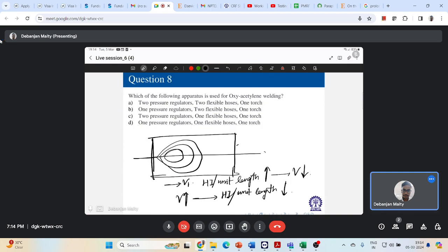Now, one more thing I want to mention over here. Let's say you are keeping all the variables constant, right? And you are changing your welding speed. So with all variables held constant, your weld penetration depth will attain some maximum at an intermediate speed. And if your welding speed is excessively low, the arc strikes a large molten pool, and your penetrating force gets cushioned by your molten pool.